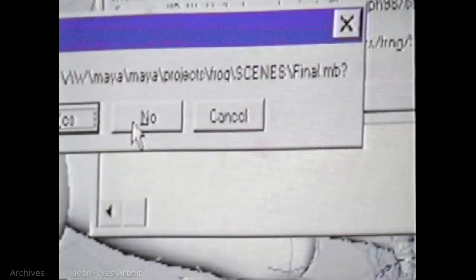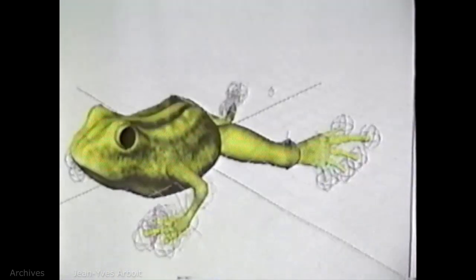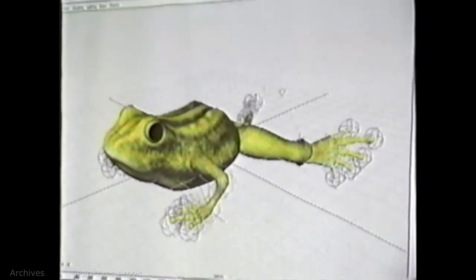It's not enabled by default. They should have put in a big window GUI. So I have to do dirmap again, dirmap -en for enable, and then hit 1, because it's just Boolean, on or off. I apply that. Now when I open up my scene, we have our textures. Very cool. Okay? Are they reference textures?